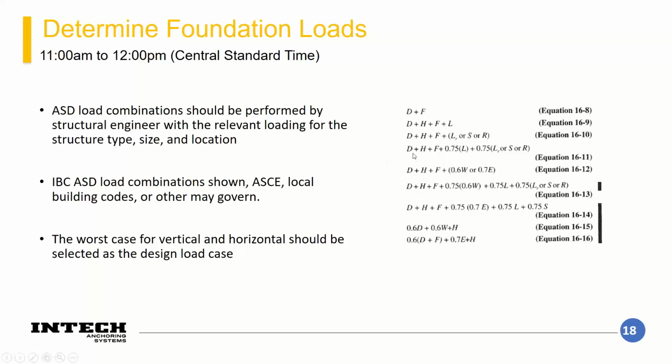So, I mean, you may have earthquake loads and wind loads, but that doesn't necessarily mean you're going to have a hurricane gust of wind during an earthquake with a foot of snow on the roof at the same time. So some of these get factored down or omitted when you're looking at these different load cases. And the reason for that is, you don't want to be so totally over conservative that it drives the cost up. So these load combinations are usually fairly similar from governing body to governing body. And it's really just the combination of all those load types we just talked about.